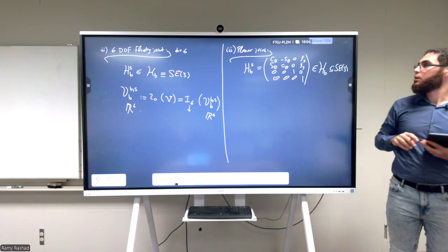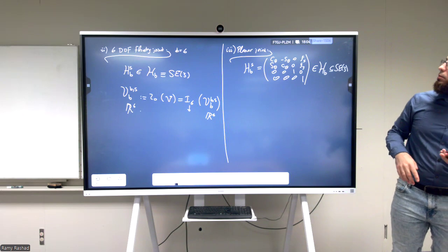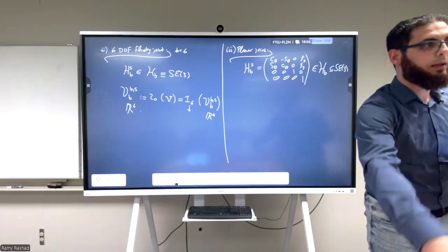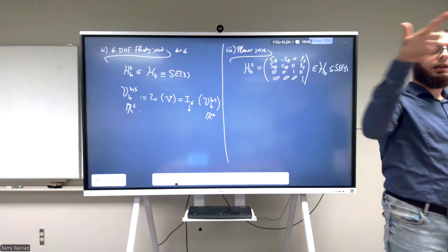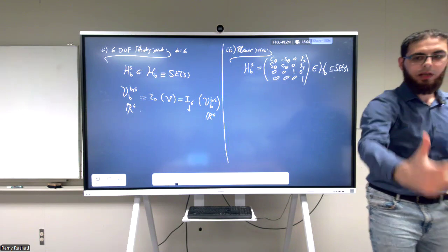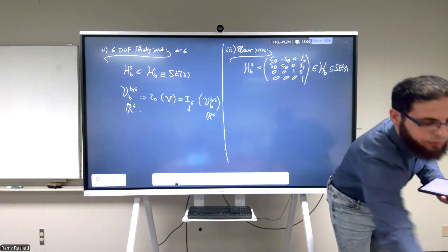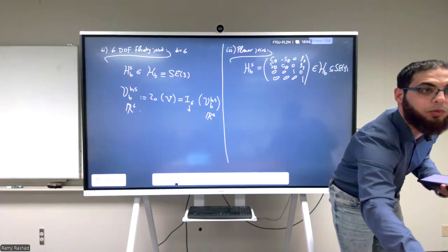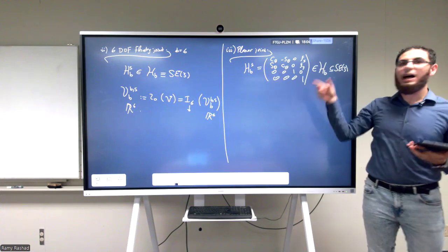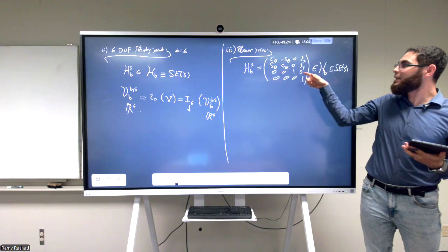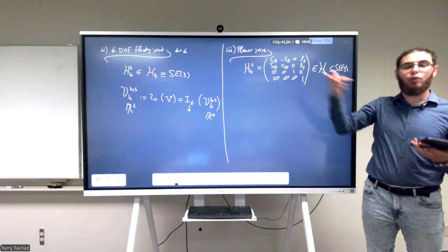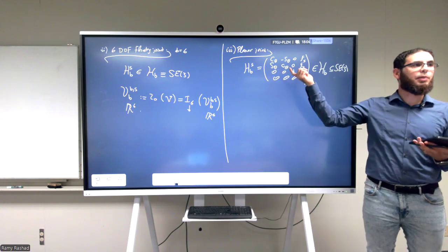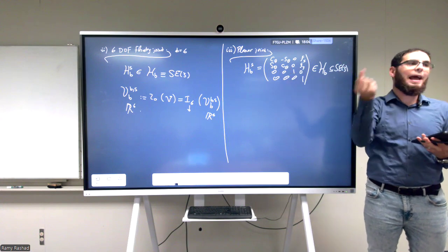It is a rotation around Z. So for this planar joint, let's assume that this is the frame I chose. This is X, this is Y, and this is Z. So you see I can move in X. I have an X displacement, a Y displacement, and a rotation around Z with some angle theta. And this is how the H will always look. I'm not allowed to have any displacement in Z. I'm not allowed to have any rotations around X and Y. This is why the rotation matrix becomes very simple, equivalent to only one angle theta.